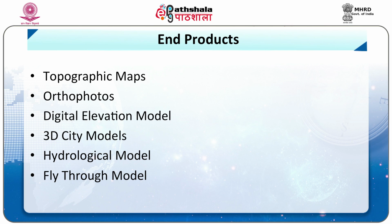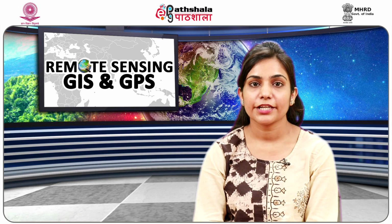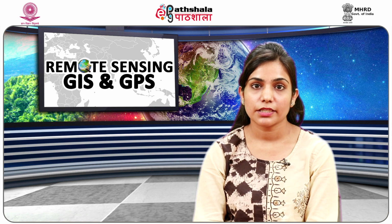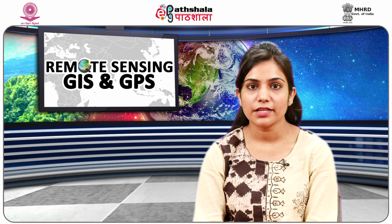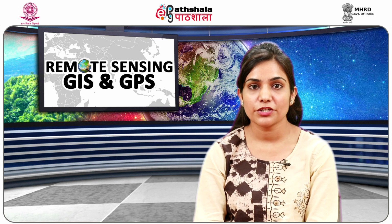Now coming to the end products, we will get topographic maps, orthophotos, digital elevation models, 3D CAD models, hydrological models and fly-through models. Coming to the advantages of photogrammetry, first, it covers a large area quickly. Second, it is low cost, though flights are costly, but it provides more applications. Next, it is easy to obtain information of areas inaccessible from the ground by air. It illustrates great detail, and last is 3D visualization.